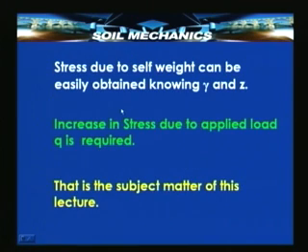Further, as I said, one component of the stress is the self weight, but then it can always be easily computed if we want by knowing gamma and the depth z, because we have just seen that the vertical stress due to the weight is gamma z. So, it is only the increase in stress due to the applied load which we are interested in, and that is what we are going to discuss in today's lecture.